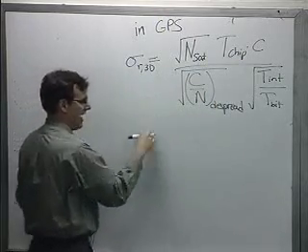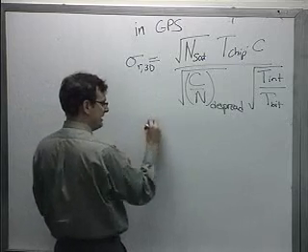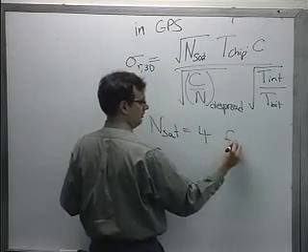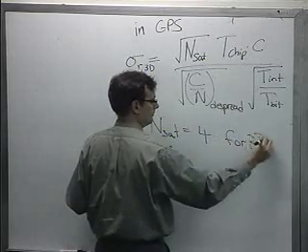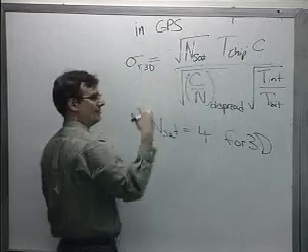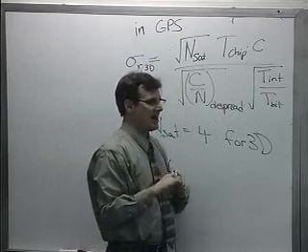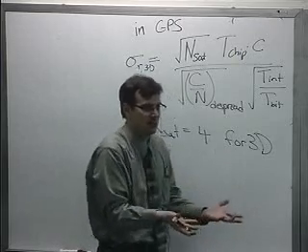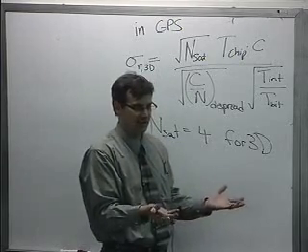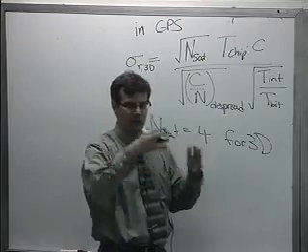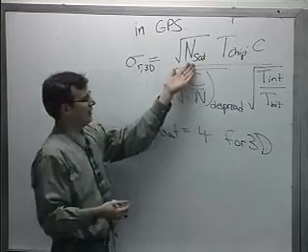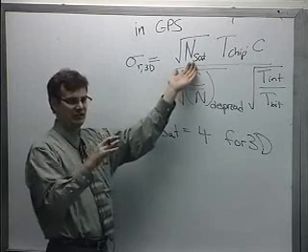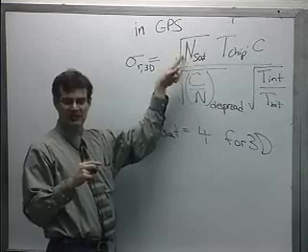Okay, and for 3D, we need 4 satellites. And this term really comes into play just because you've got 4 dirty measurements being folded into your estimation of range, and that range is going to be so many meters off. And so it's going to increase because you use more pieces of information that each had a certain uncertainty to it. So that's why this goes up.